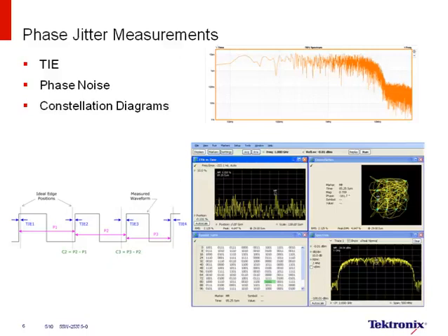The second question is, for a target BER, like 0 errors over 3 days, can you determine what the TJ must be at a transmitter output of the PHY? So again, very similar. You can do almost the same thing. As you characterize the TJ, you want to make sure what the correlation is to the BER receiver. So again, like the first question, the key thing is to understand what the receiver silicon is doing. Now, your next question might be, well, how do we know?